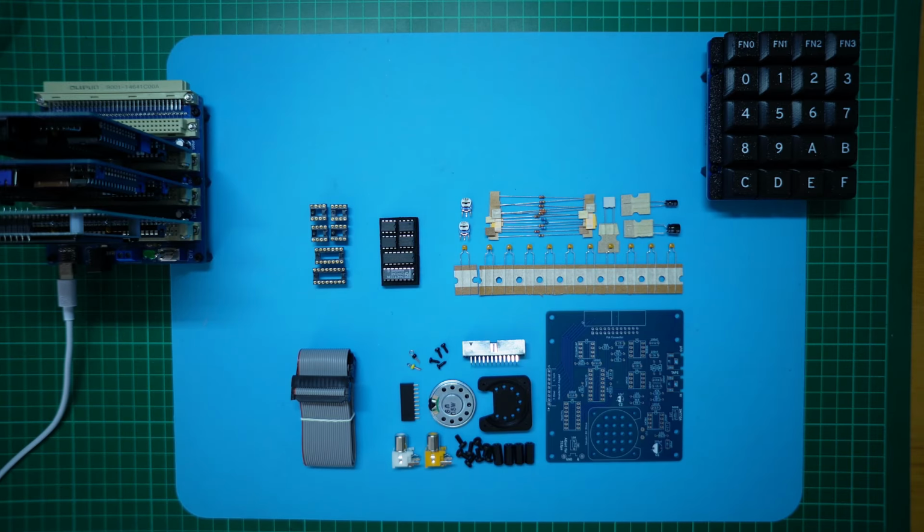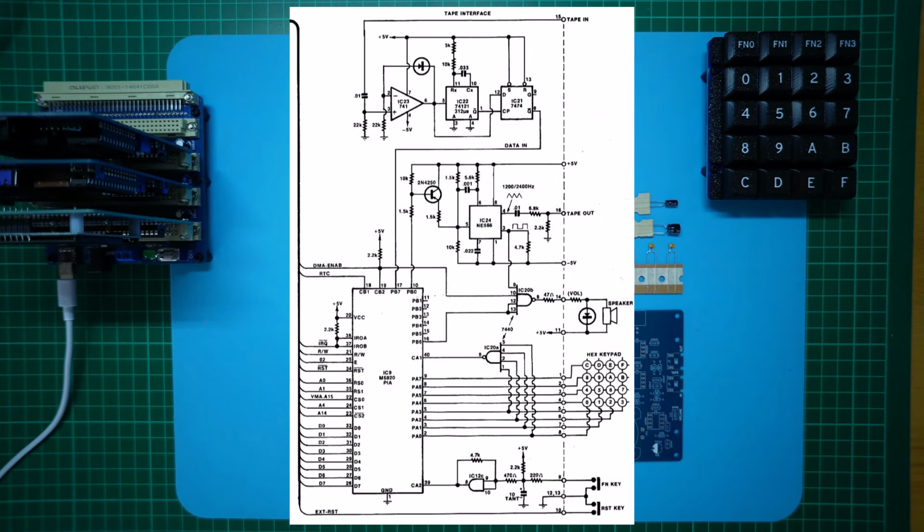For reference, here is Michael's original schematic for the matrix keypad, tape interface and the sound interface for the original Dream 6800. As you can see, it uses the now very hard to find NE566 function generator, a 741 dual supply op amp, as well as a 7440 dual 4-input NAND gate, and a 74121 monostable multivibrator. The 74121 is still available, but is now relatively expensive.